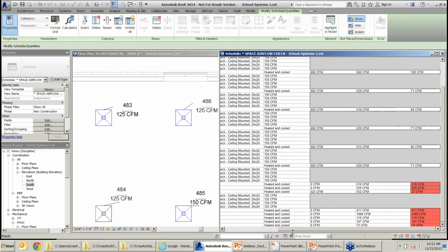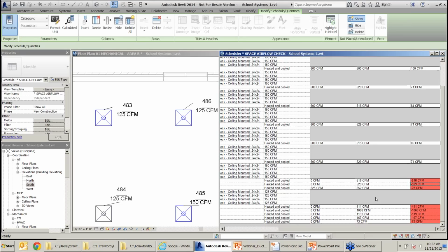What if you have a space and air terminal with a CFM, but the space doesn't list a specified supply airflow, or calculated airflow is not computed? Oh, okay. I don't want to dive into that too much because that could be a much longer discussion, but I'll show you really quickly. So let me finish my... Can't you calculate your own? You can. A basic calculation without the engineer of the space, right? Yeah, and you can type that in. Revit has 3 different... okay, let me finish this one thing and then I'll dive into that for just a moment.